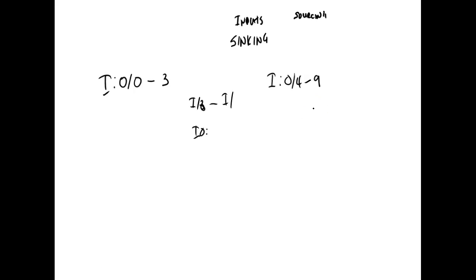So if we want to hook them up sinking, what do we need to do? Your fixed PLCs have an internal power supply. For modular PLCs, you buy a power supply module, or you can use an external power supply. When we were over there on the 914 Siemens, they had an external power supply.